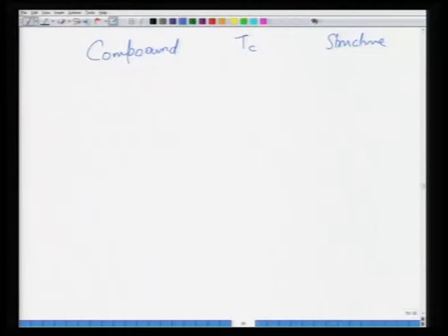The first thing you can have is yttrium based, which was of course YBa2Cu3O7. I am not giving the non-stoichiometry here. Most of these oxides show superconductivity in some sort of non-stoichiometry, and the highest Tc achieved was 92 Kelvin, with an orthorhombic structure.